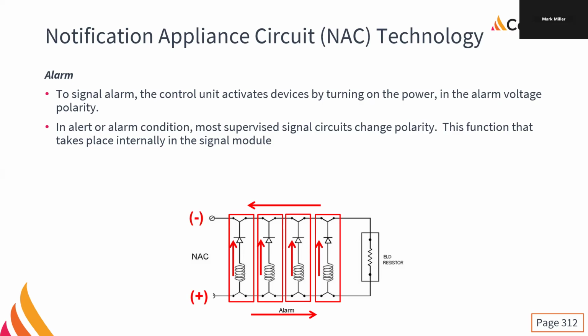Well, fire alarm panels work on 24-volt DC, and most of us carry 18-volt batteries for our cordless tools. Signaling devices will run pretty good on 18 volts. So there's our test battery. We can just hook them up in one direction, make sure they all ring. If we hook up in the other direction and none of them ring, well, we hook them up properly. If you hook them up and one of them isn't ringing, we can figure out where the issue is because then we can hook it up reverse polarity and you will hear that one ring. Oh, yeah, that one's backwards.